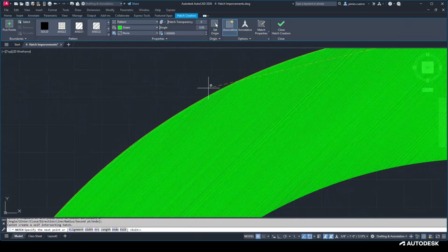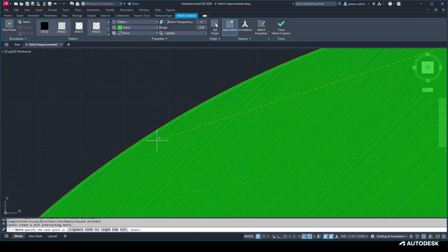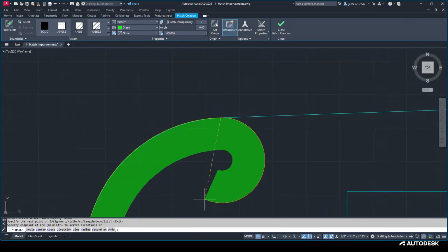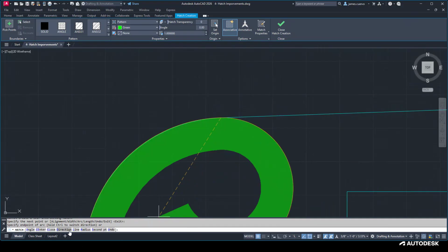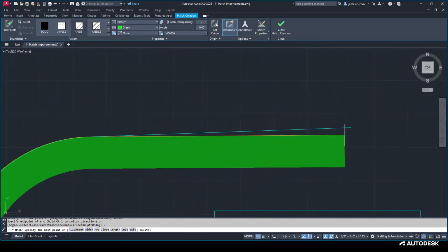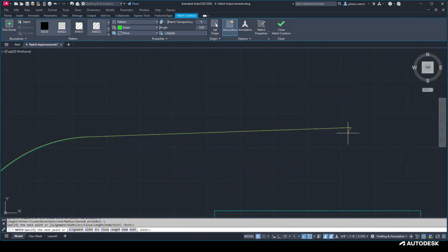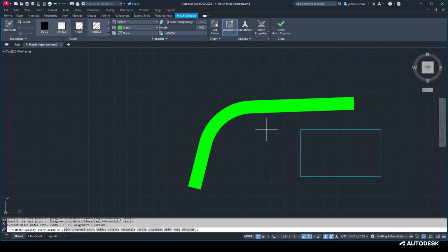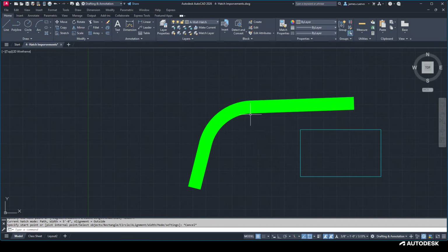Be careful, it doesn't necessarily adhere to the arc that we have drawn. You have to come back and adjust that. Then we have to switch back to line, and finish defining our line. Hit the enter key to finish, and we terminated the item. Then hit the escape key, and this is set up.